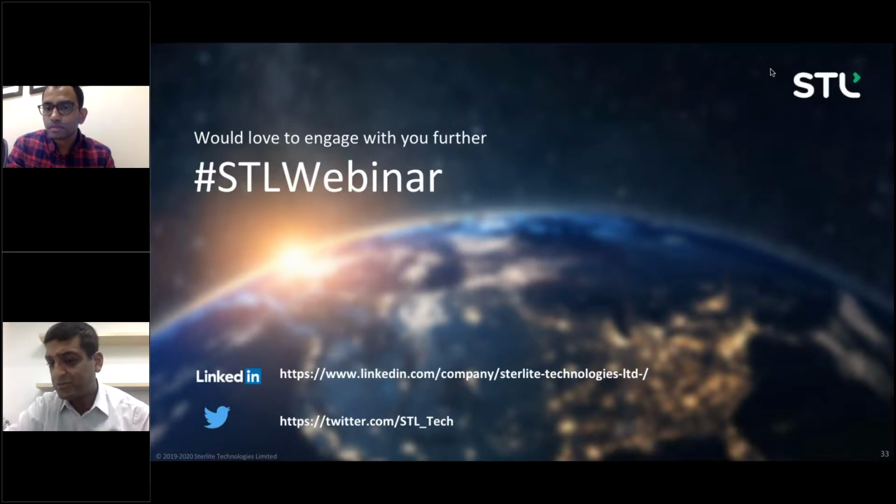We believe we've answered the question with the introduction of Stellar, and we definitely hope that using it in the networks will solve that particular problem where you have the MFD mismatch across different pieces of your network. Stellar should pretty much take care of that, make it compatible with legacy D fiber. It will have a mismatch with any A2 fiber which has an 8.6 MFD, but those are not very commonly deployed yet in India. And with this, we actually think that we can bring the benefits of G.657A2 into Indian networks while still retaining the compatibility with the G.652D legacy networks.